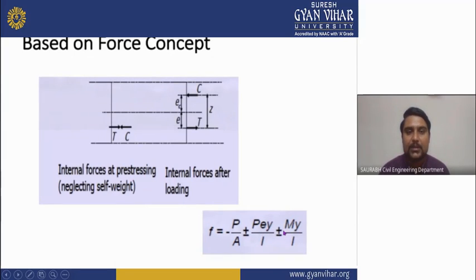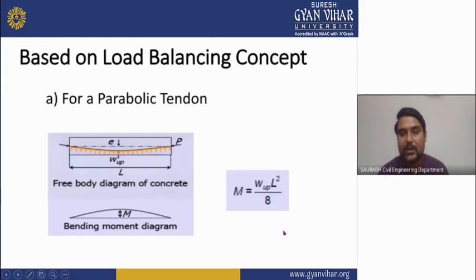Now we will see the force concept here. As you can see, the internal forces at prestressing, neglecting self-weight, and the internal force after the loading are shown there. F will be equal to minus P upon A plus minus P e y upon I plus minus M y upon I.